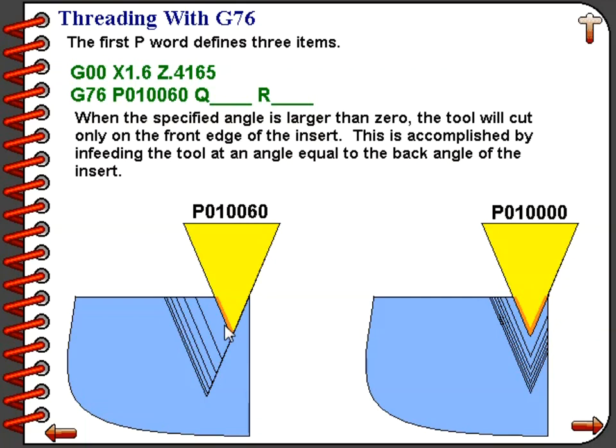This has a lot to do with the surface finish of the thread after it is completed with the machining operation. Generally speaking, it is most ideal to always specify the proper nose angle for your insert and thread. For acme threads that are square in shape, you would specify a 0, 0 for your tool nose angle.